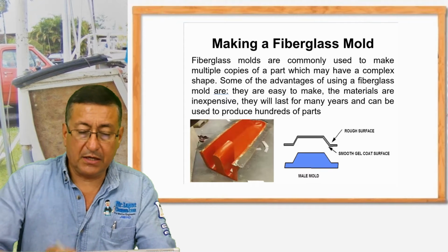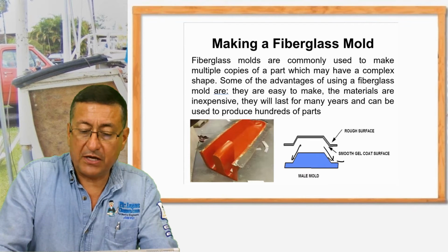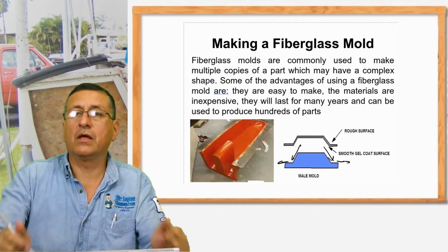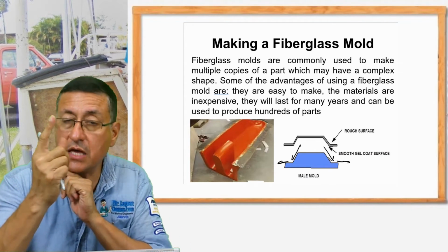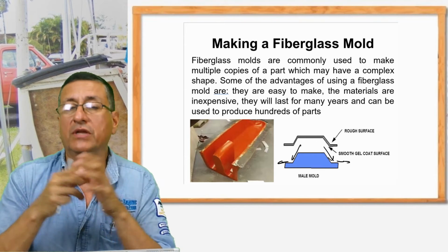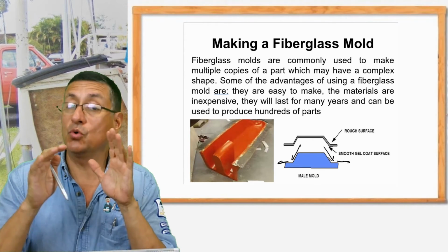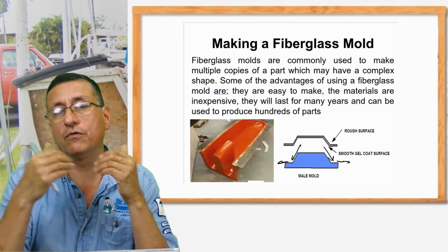Remember that the most important part is the angles, the inclinations, and the flange. After that, it is easy to remove the mold. The plug, once again, is used one time to create the mold. Once you have the mold, you can destroy the plug, and you store it, you polish it, you keep the mold in great condition for years and years.